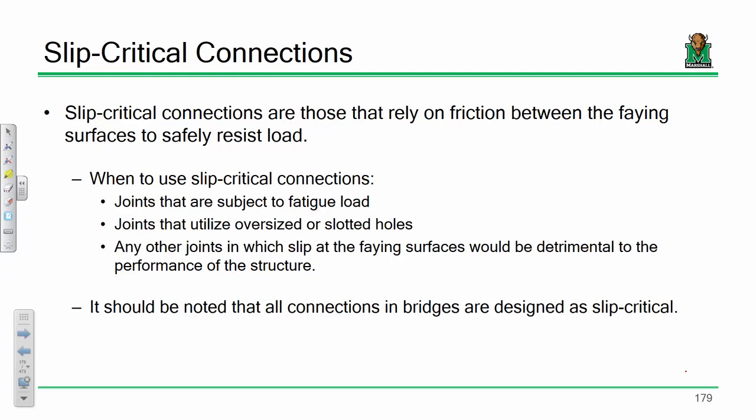So the same thing's sort of true on a bridge, but instead of the vibrations being so fast, like they would on a lawnmower, just imagine a loose bolt on a bridge after 20, 30 years. It's just going to fall off, right? So in bridge land, we always ensure that those bolts are slip critical to basically ensure that they're going to stay there, that they're not going to go anywhere under that repetitive cyclic loading that happens over its design life. So yeah, I just wanted you to be aware of that.